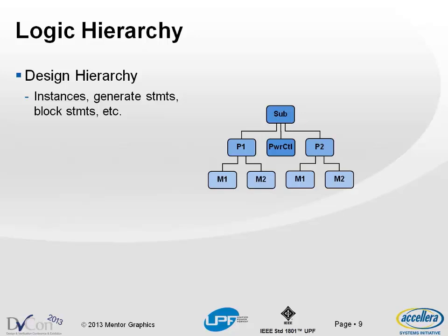It encompasses any kind of hierarchical structures, including things like subroutines defined inside of packages, generate statements defined inside of blocks, etc. In UPF, we have a slightly more abstract idea of hierarchy. We're only looking at the hierarchy of instances, and that is usually called the logic hierarchy in the UPF spec. So I'll be talking about logic hierarchy here, and I mean the instance hierarchy, in particular, not talking about generate statements, other nested internal blocks, by and large.